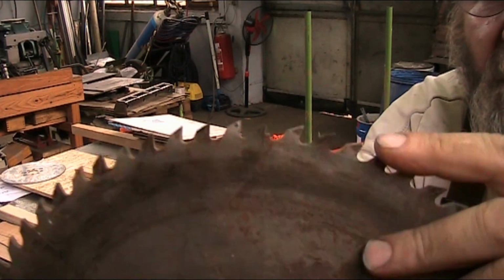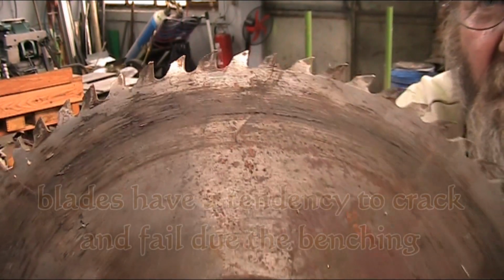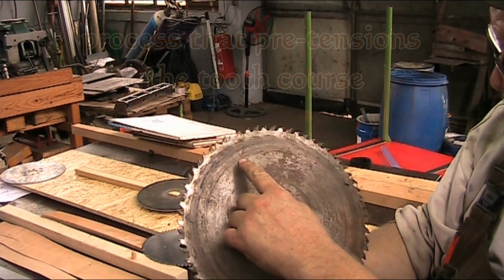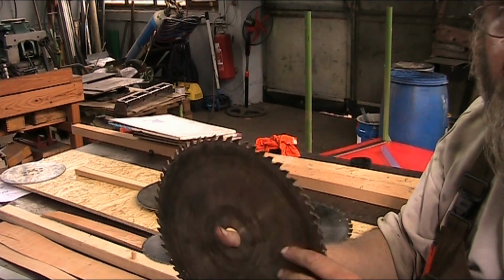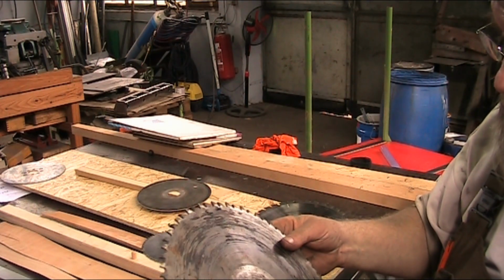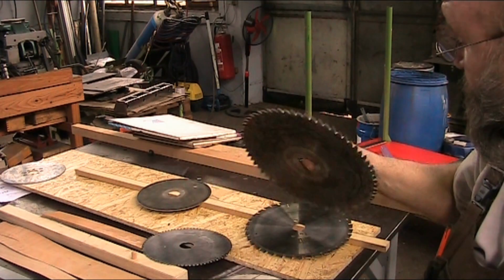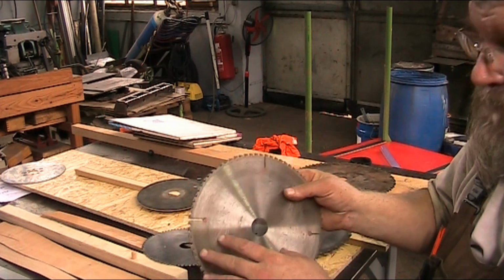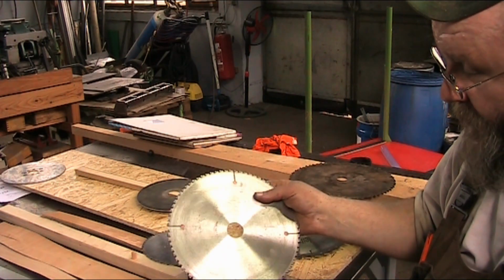And the reason they do that is to prevent this from happening. This blade was heated to the breaking point and it started to crack. So there's a crack here, a crack here. Yeah, there's two cracks in it. And so this blade is toast. It can never be used again, because eventually this blade will fail. It'll come apart in the saw and you'll be dodging chunks if you try to use a blade like this. So these are expansion joints to prevent the blade from cracking, because these will get quite hot, especially if you're running them for any length of time.